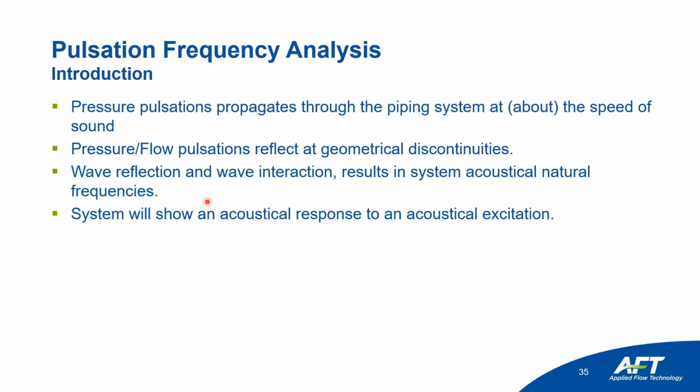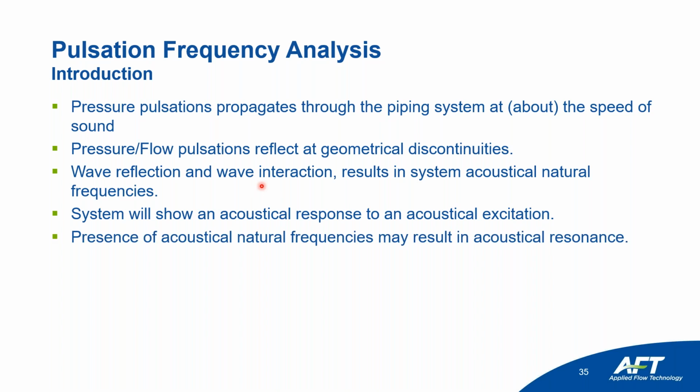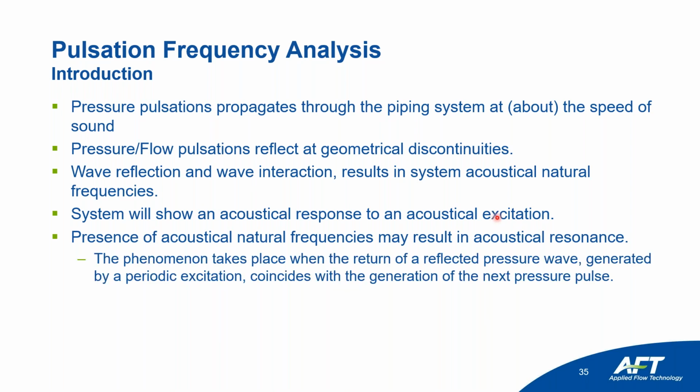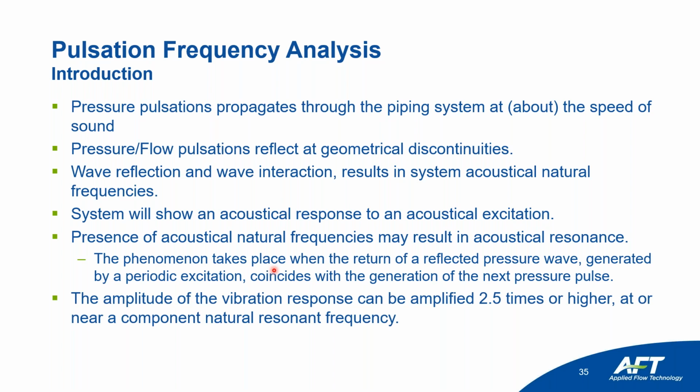System will show an acoustical response to an acoustical excitation. Presence of acoustical natural frequencies may result in acoustical resonance. The phenomenon takes place when the return of a reflected pressure wave generated by periodic excitation coincides with the generation of the next pressure pulse. The amplitude of the vibration response can be amplified 2.5 times or higher at a near component natural resonant frequency.